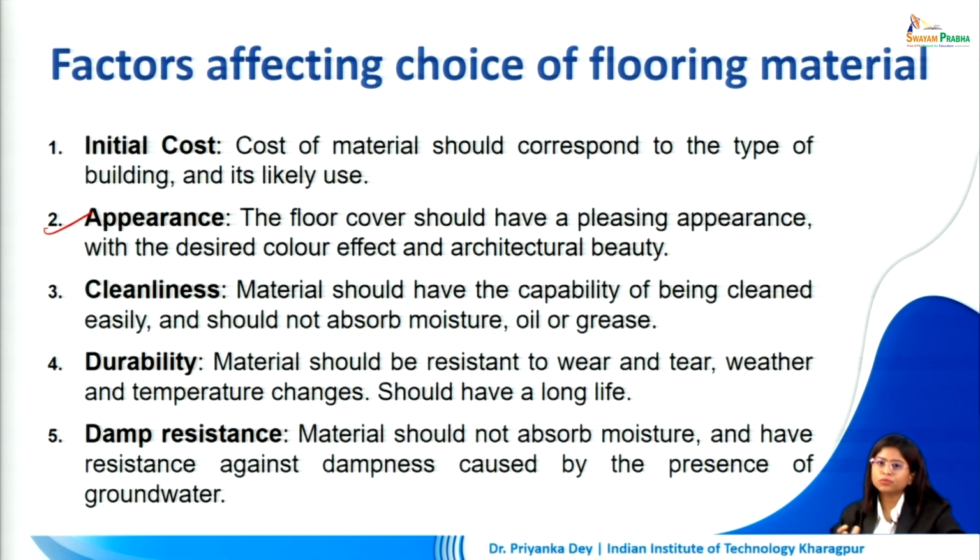It can be maintained over a long period of time. We also want to ensure that while we are cleaning it, no damage occurs to it. So cleaning it multiple times shouldn't reduce its pleasing appearance over time. So that has to be one of the important parameters to determine the type of flooring material that we are selecting. Durability is also an important aspect. Material should be resistant to wear and tear, weather and temperature changes. It should have an overall long life.